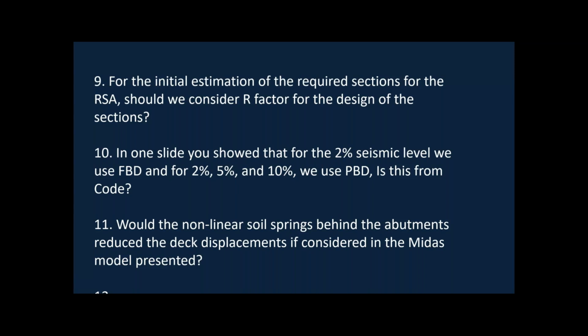Prathamesh? Yes. So coming to the 11th question, would the nonlinear soil springs behind the abutments reduce the deck displacement if considered in the MIDAS model presented? Yes, you're right. If we are considering the nonlinear soil springs behind the abutment, the deck displacements will be limited because it will provide resistance to the structure. Currently, the nonlinear soil springs are not considered in this particular model.